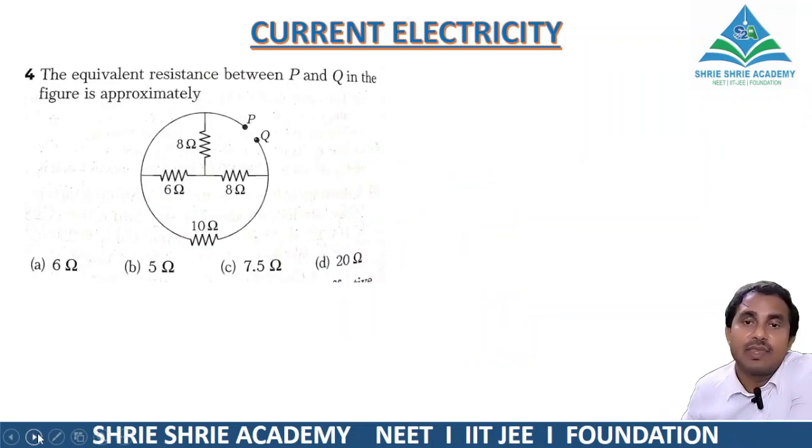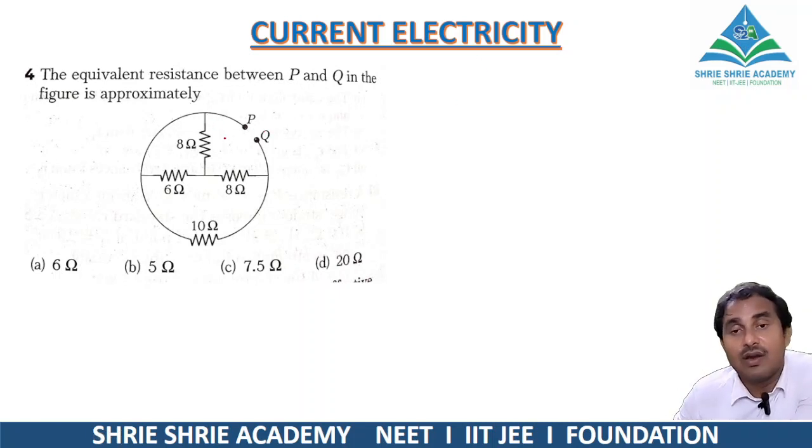Next one is equivalent resistance. In such kind of thing, our approach should be to find out how to arrange them in series and parallel connection. See, this is the one resistance. This side terminal is there, you cannot shift its end, but this one can be brought over here. This point can be shifted here, because from here to here there is no resistance connected, so you can shift this point to here.